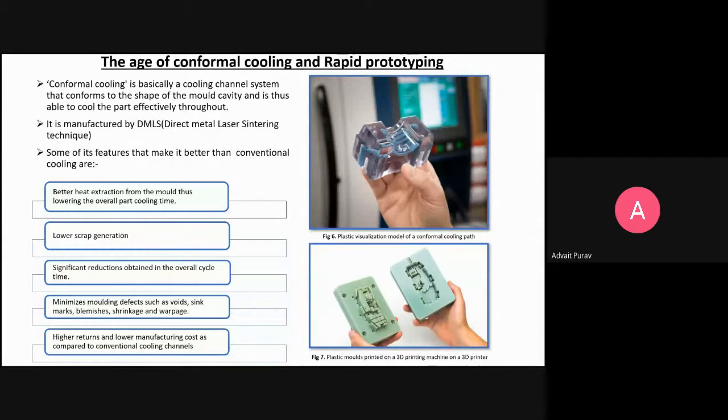As you mentioned, its computational cost is quite high, but at the same time, companies here don't use it because they are dependent on their age-old techniques. But in foreign companies it's in great use right now. Even if the manufacturing cost is high, after they finish manufacturing that part, they get output with very little warpage and shrinkage, and cooling time is reduced by 2-3 seconds. If it was taking maybe 15 seconds, it has come down to 8 or 9 seconds.